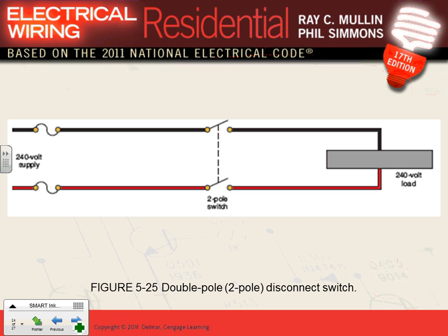Okay, 2-pole switches. When do I use 2-pole switches? You use 2-pole switches on anything that's a 2-pole load. 2-pole means 2 hots, means 2 phases, right? So I have a fixture. I'm going to burn this fixture at 208. I'm going to switch it and burn it at 208. The only way you can get 208 in the US is from 2 hots. You can't get 208 from a hot and a neutral, right? Everybody knows that? The voltage hot to neutral is 277 and 120 here.